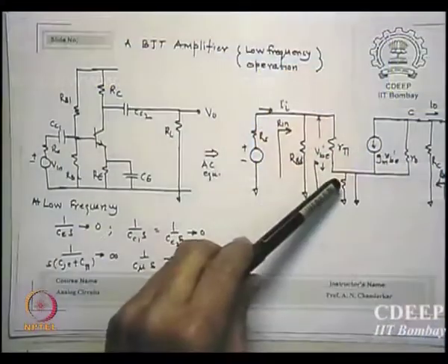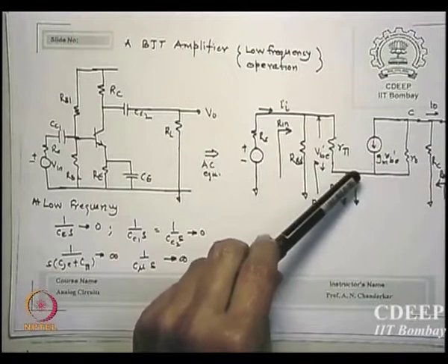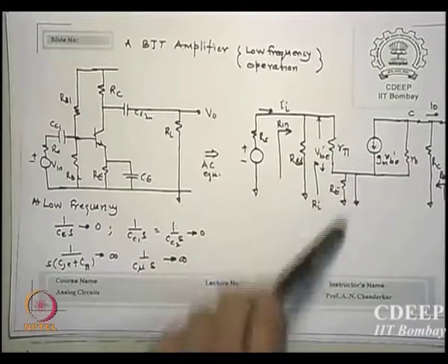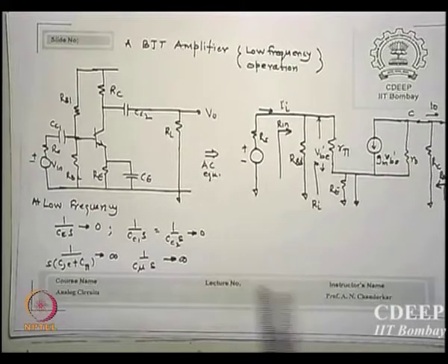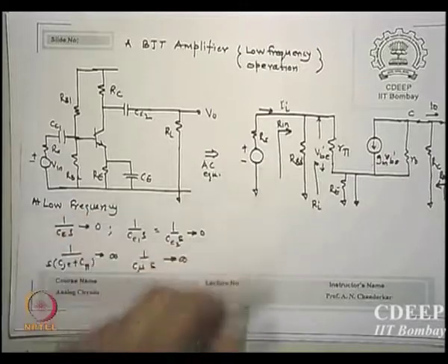Now you can see, sorry, I forgot this, I still drew RE for AC. So what did I do? I actually put a short across to show RE is shorted. The C will bypass DC at the time, but for AC it will short the RE itself. Okay.